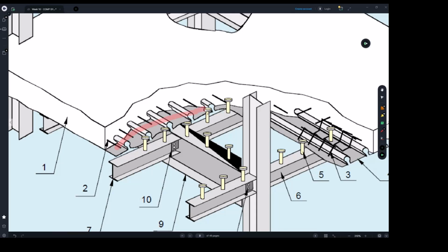This is a metal sheet. You see it comes with this special profile shape. We use it a lot in construction. It's got two main functions. Number one, it helps to improve the strength and add that composite feature. And number two, it works as a permanent formwork to carry the wet concrete, so you don't need to spend a lot of timber to form up the slab. The bond is going to be there. Sometimes you just need to put one propping line to carry it.